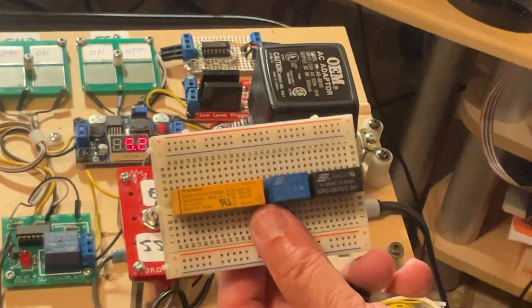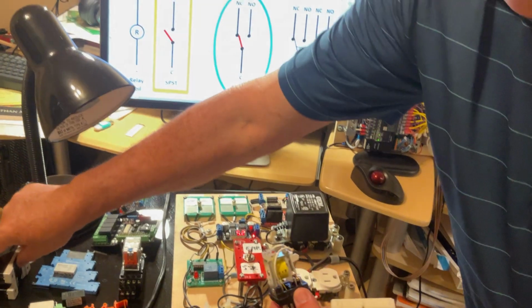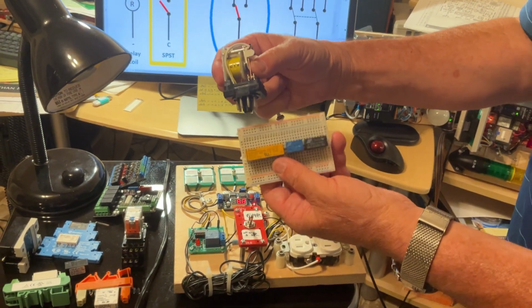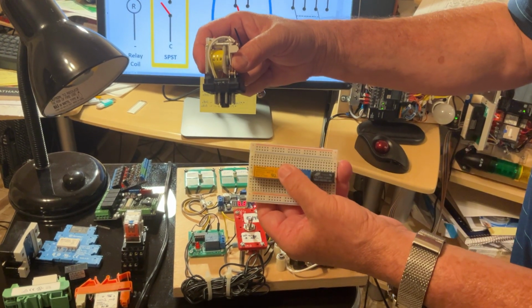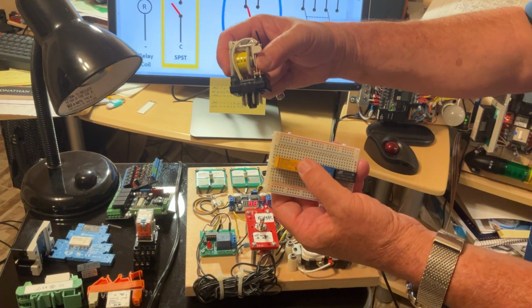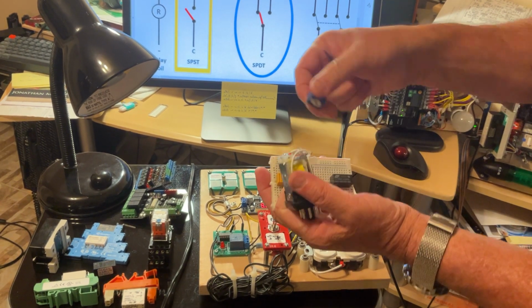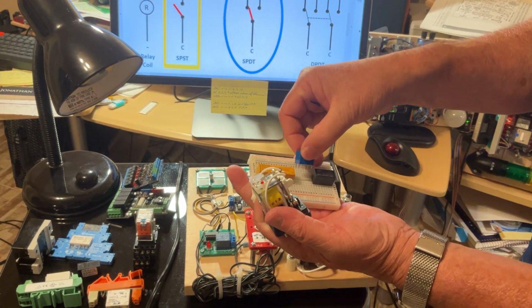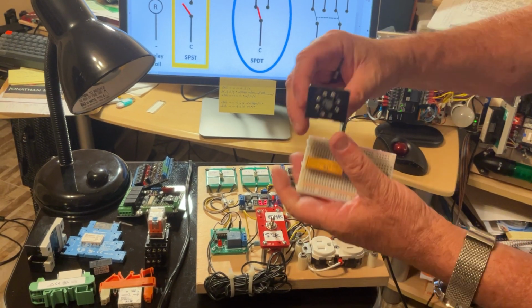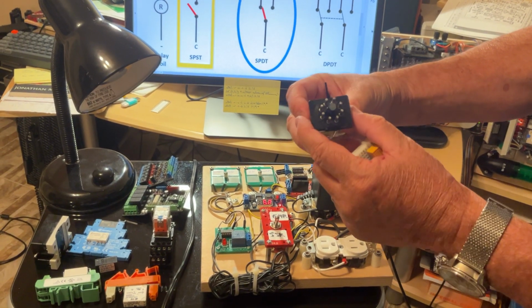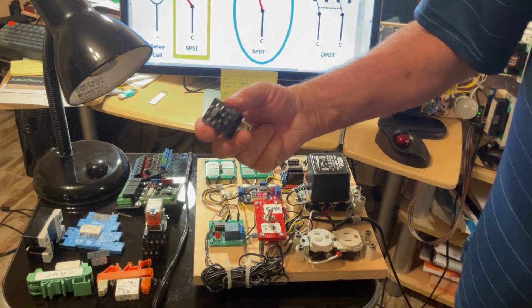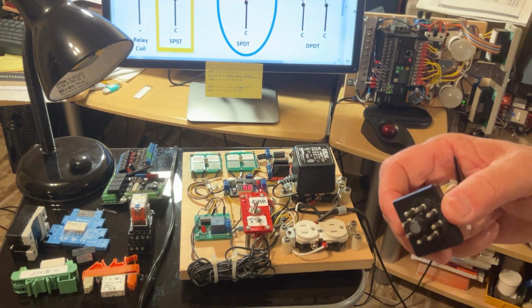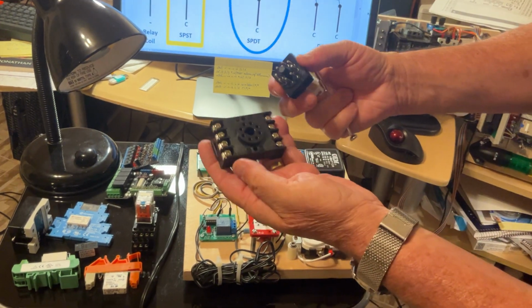So, 2 kinds of classification again. One classification says electromagnetic versus solid state. Second classification for electromagnetic relays, basically, between classical construction and PCB relays. The PCB relays, by the way, they have very tiny terminals. This is why they can be placed on a breadboard or they can be soldered, versus the standard electromagnetic relays, which are used in most of the cases placed on a socket.